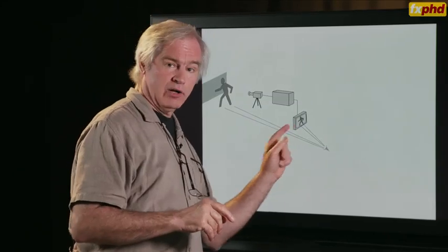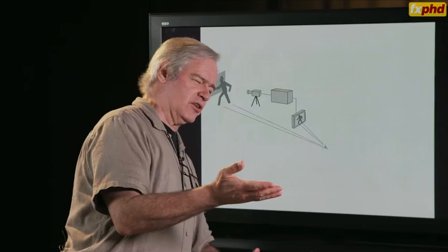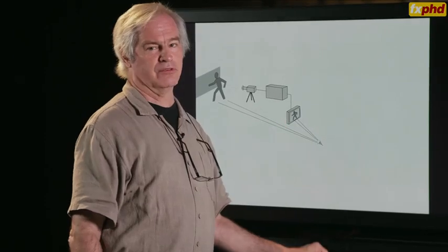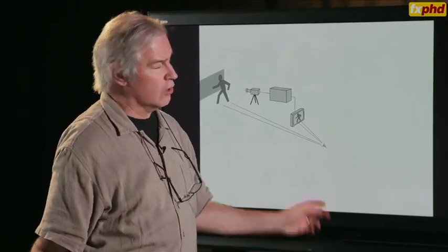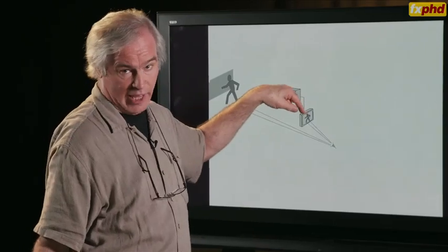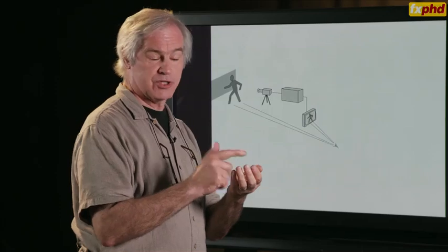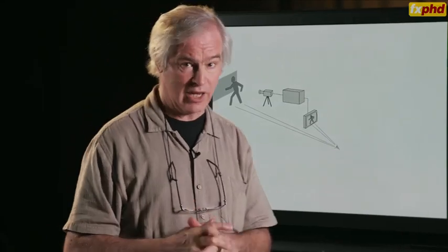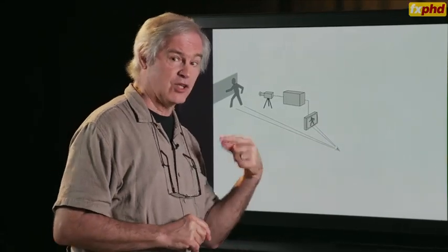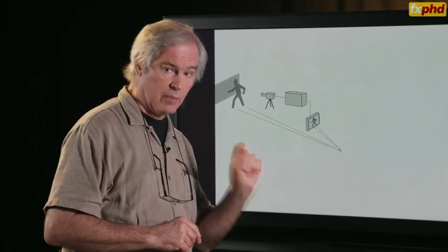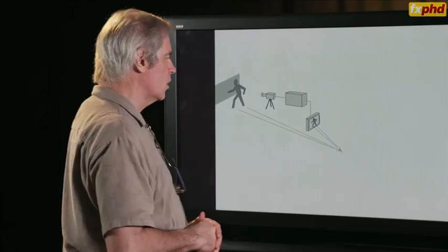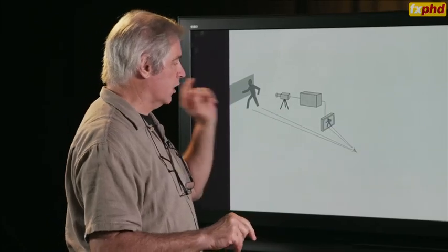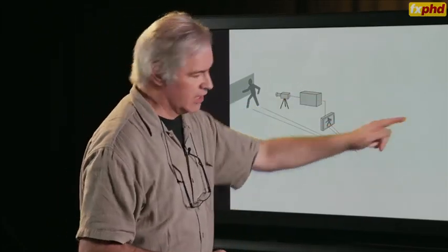All bets are off on flat panel displays, or if you want to call them fixed pixel displays, because they don't share the physics of a CRT. And so now we need to standardize that electro-optical conversion function, and that's the importance of BT.1886 that I mentioned last class. Standard for HD display, a power function of 2.4. So now back to the main storyline. We're going to take that image and distribute it to the end consumer.